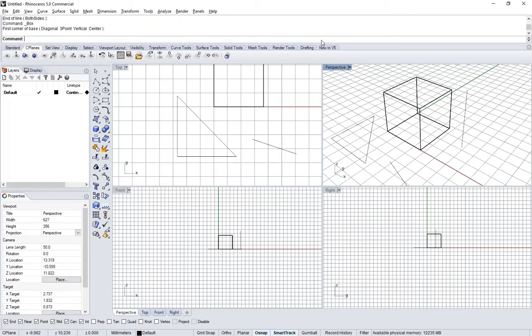So in addition to typing the full name of the command directly into the command prompt, Rhino also allows you to associate smaller keywords with the commands, which allows you to enter them much more quickly. And these are called aliases. This is the 4th way to issue commands into Rhino, and because the names can be shortened, this is by far the quickest way to work with Rhino.